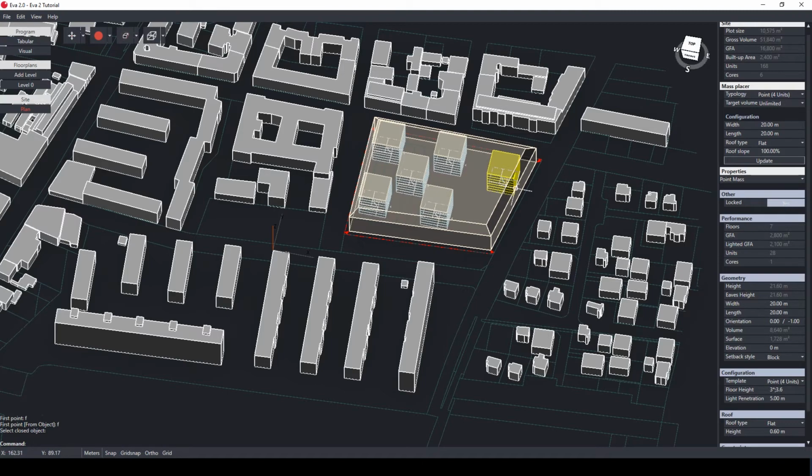For the other houses, I would like to have different roof types. To do so, we have several possibilities. I choose the roof type HIP and go to Update. Now my buildings have roofs. This means that the roof space is being fully used and the houses with the sloping roofs are shifting to the building line.